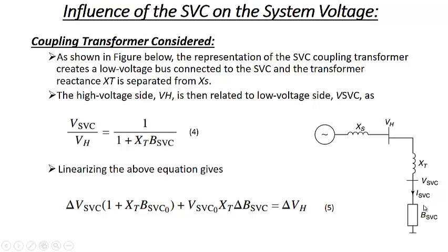Let's say it is XL divided by XT plus XL, multiplied by, of course, VH. I will divide the reactance part by XL on the numerator side as well as on the denominator side. So it will be equal to 1 divided by 1 plus XT divided by XL, where 1 by XL can be taken as the susceptance of this. That is what this is.